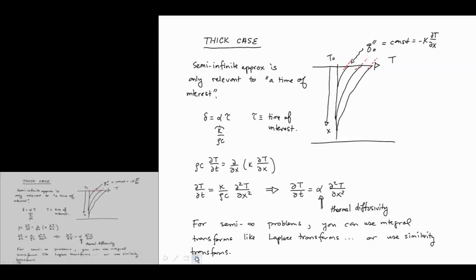If you think about the actual ignition of a material, even if it's a thin sample, so if I had a lamp heating up this piece of paper, it would start to blacken and char perhaps before it actually ignited, before a flame was supported above it. It's hard to imagine that the properties don't change as this decomposition process is happening prior to ignition.